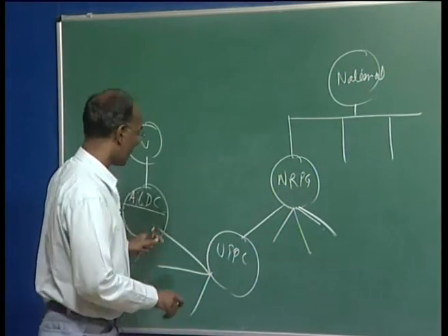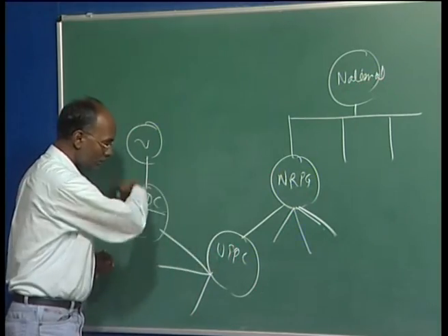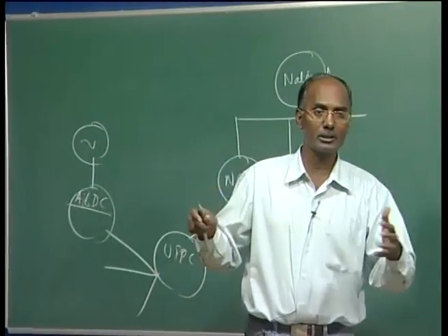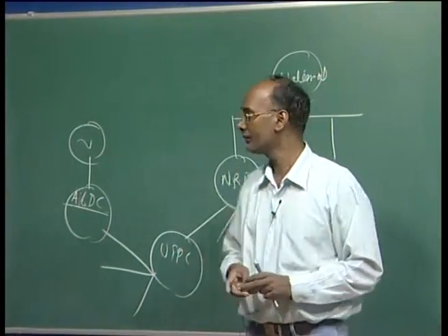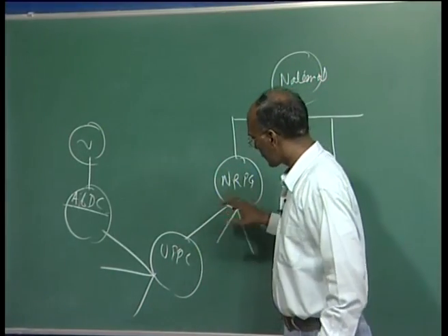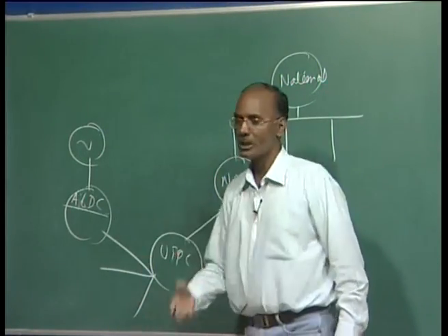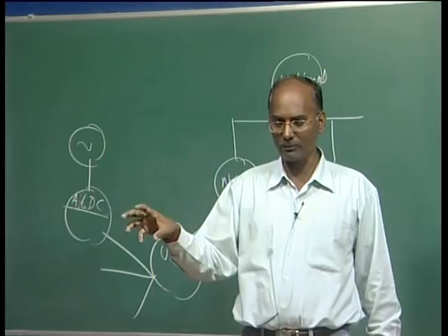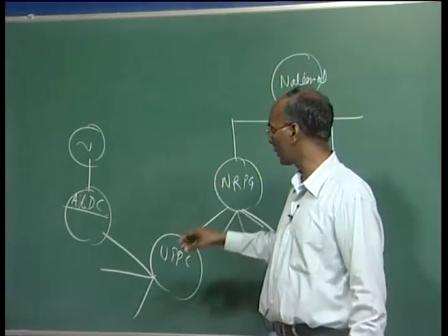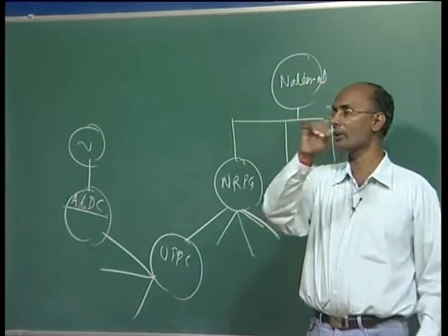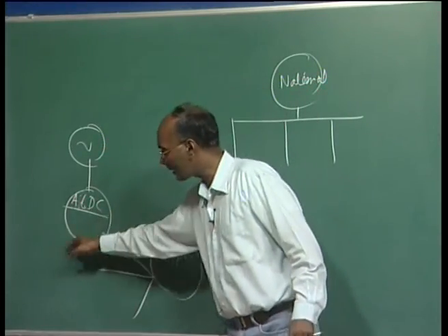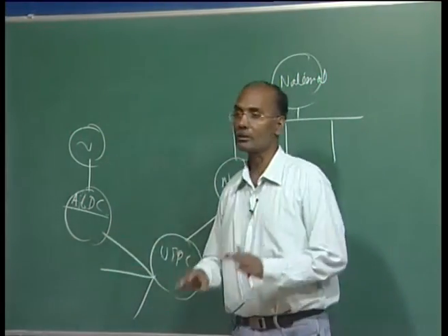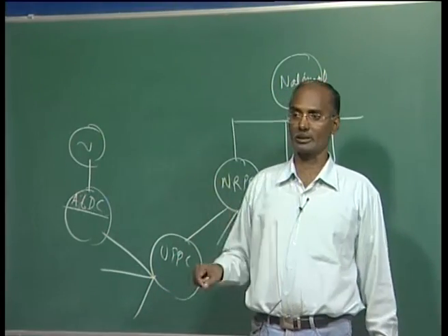So, in the operation, all these persons who are sitting here normally go for the load generation balance. They should know what the voltages and the frequency in the system are. Based on that they can go for the load generation balance. So, sitting here, in the whole system we have the remote terminal units, meaning each substation is equipped with monitoring devices like CTs and PTs. That information comes here, and the person sitting here can see the power generated by the generating units, the load taken by the various feeders, and also the power flow and voltage at the various nodes, through the state estimators.